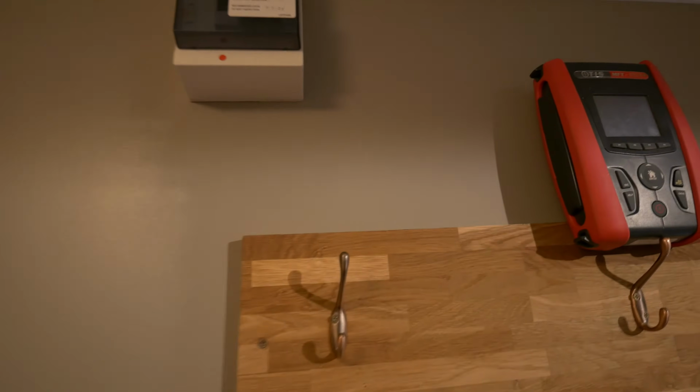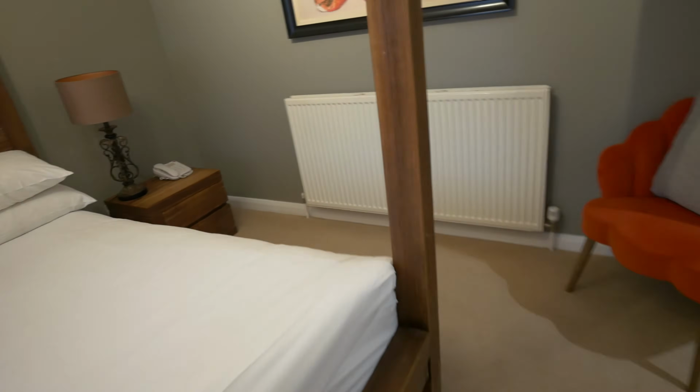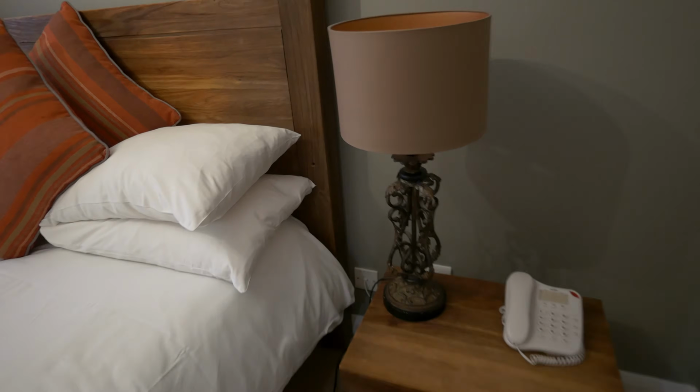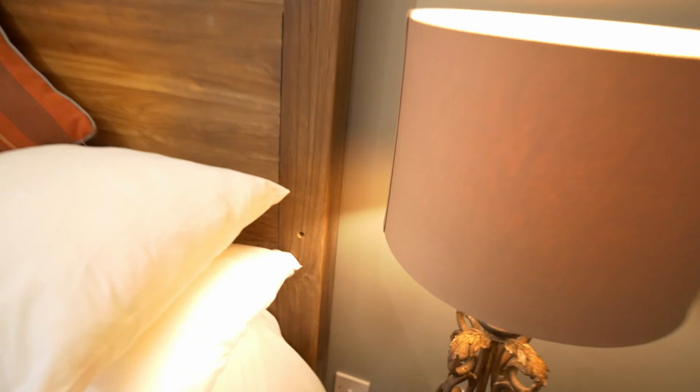So now first up, if we pop the power off while things are on and functioning, it's a really simple way of checking what is exactly on what circuit. Actually, before we do that, I'll just make sure all of the lights and lamps are on. That's one of them popped on. Let's stick this one on. And we've got everything else on and working. It's just a really quick visual way of identifying what's doing what without getting any test instruments out.